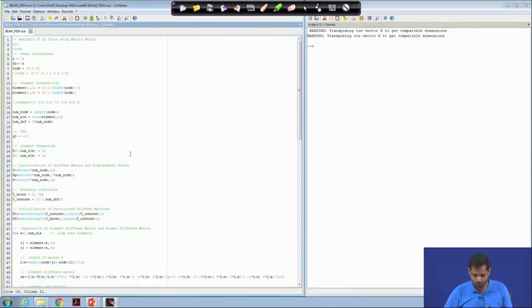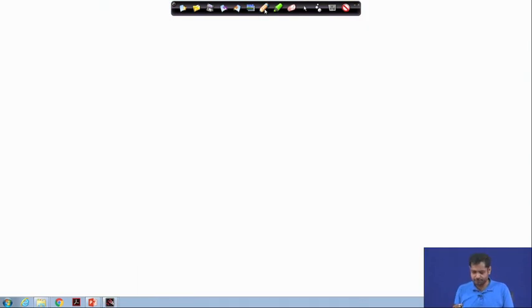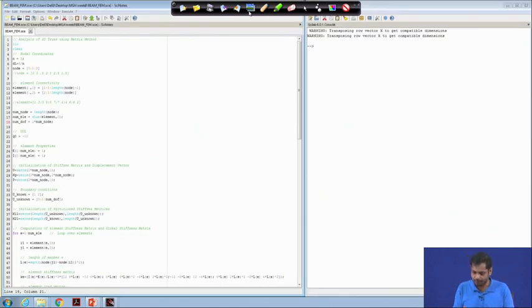okay. So, this is the code. So, consider a problem like this. The problem we are considering is this. Okay. Take a cantilever beam, then it is subjected to uniformly distributed load. We will come to the point later. Suppose the length of the beam is 3 meter. Okay. Entire length is 3 meter. Now, let us divide that beam into, say, 6 segments. So, we have just 1 point, 2, 3, 4, 5 and then 6.